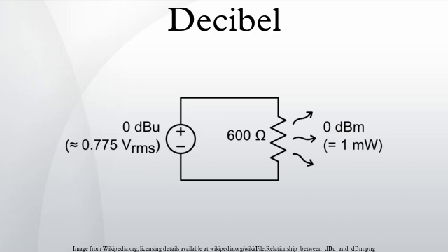Voltage. Since the decibel is defined with respect to power, not amplitude, conversions of voltage ratios to decibels must square the amplitude, or use the factor of 20 instead of 10, as discussed above. dBV: decibel, VRMS, a voltage relative to 1 volt, regardless of impedance. dBu or dBv: RMS voltage relative to 0.775 volts. Originally dBv, it was changed to dBu to avoid confusion with dBV. The V comes from volt, while u comes from unloaded.